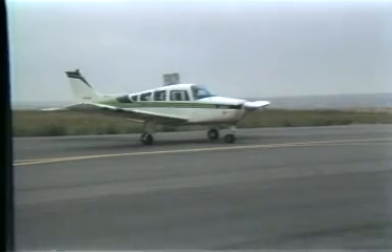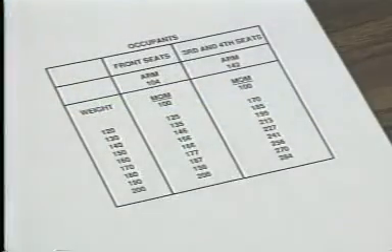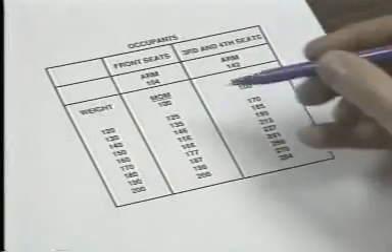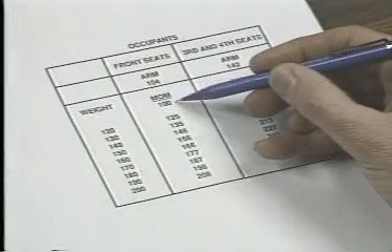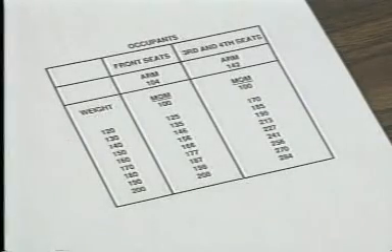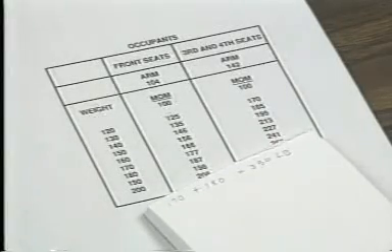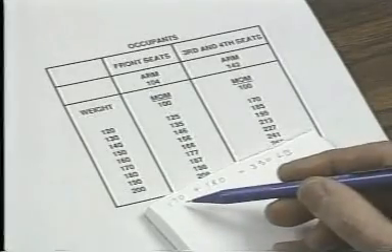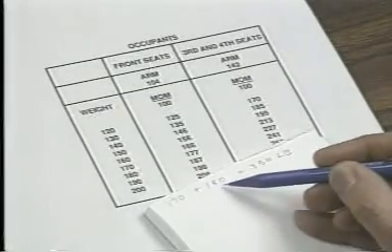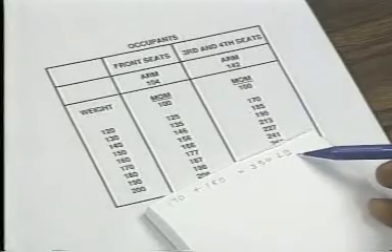Another simplified method of determining moment is the table method. It requires only that you locate a given weight, then find the corresponding moment. Notice that the moments in this table must be multiplied by 100 to compensate for the reduction factor. Also, if a single weight exceeds the limit, you should use two lower weights which, when added together, equal the single weight. For example, you know that you and the front passenger weigh 350 pounds.